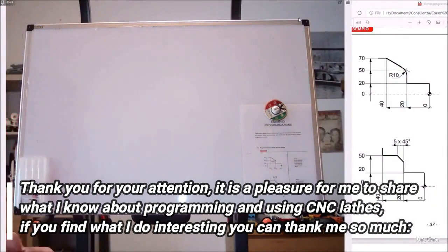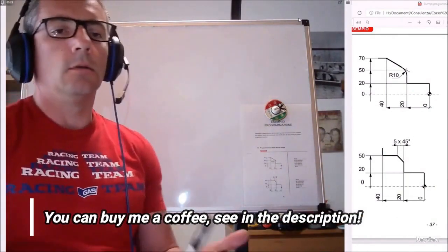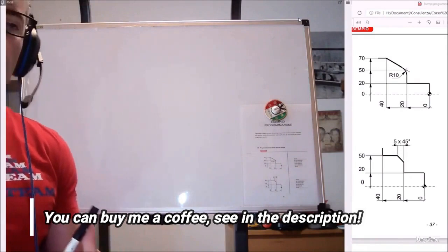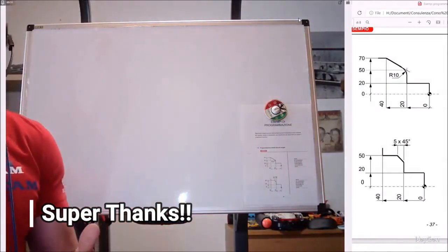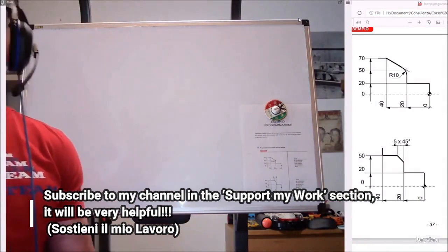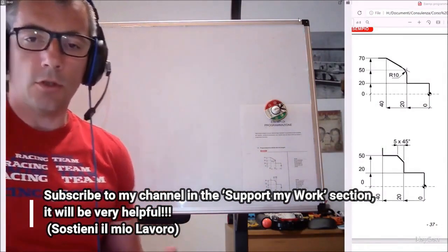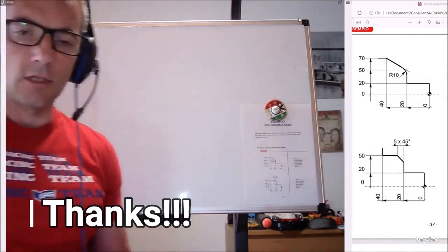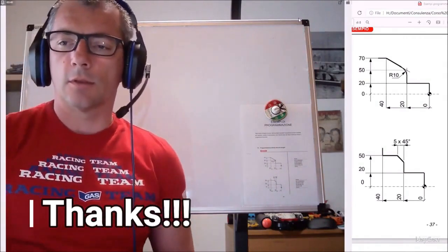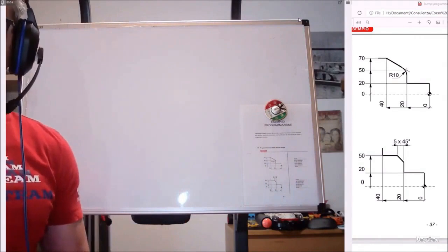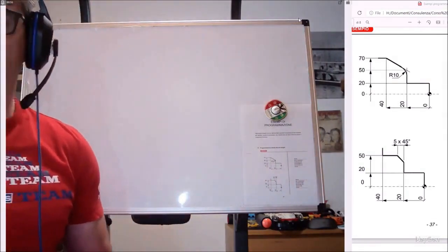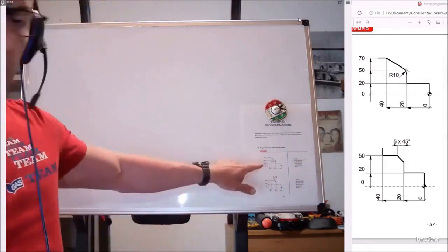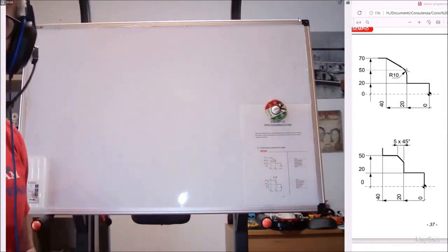In the last lesson we saw that we can move in G0, G1, G2 and G3, thus in a linear manner, in rapid linear motion, in working linear motion and in a circular manner. These are the interpolations: linear interpolation and circular interpolation. As you can see today on our screen, I see it on the right. I don't know if you will see it flipped on the left. We have programming examples, examples of programming that can put us in difficulty.